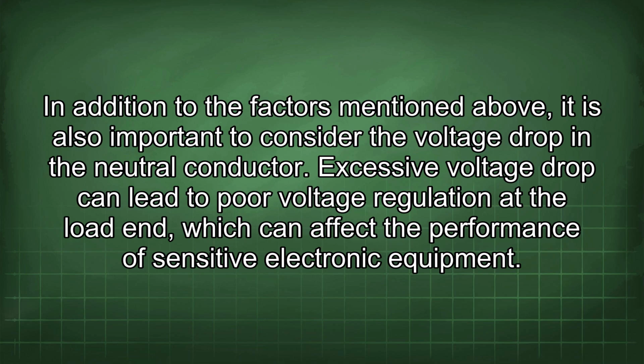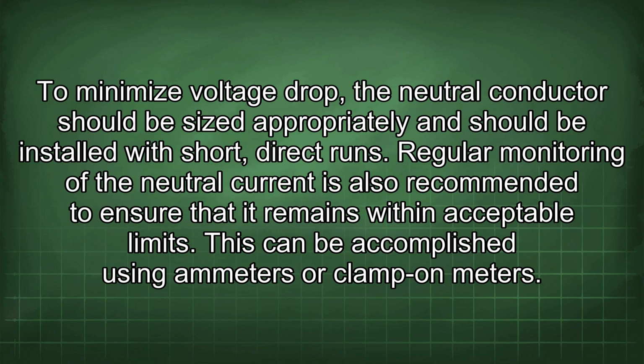In addition to the factors mentioned above, it is also important to consider the voltage drop in the neutral conductor. Excessive voltage drop can lead to poor voltage regulation at the load end, which can affect the performance of sensitive electronic equipment. To minimize voltage drop, the neutral conductor should be sized appropriately and should be installed with short, direct runs.